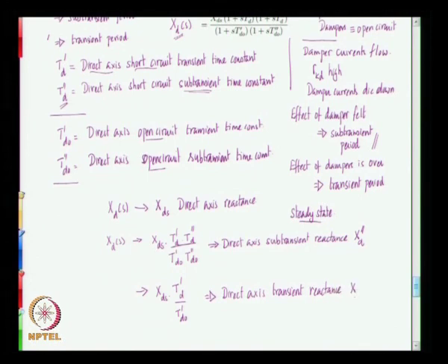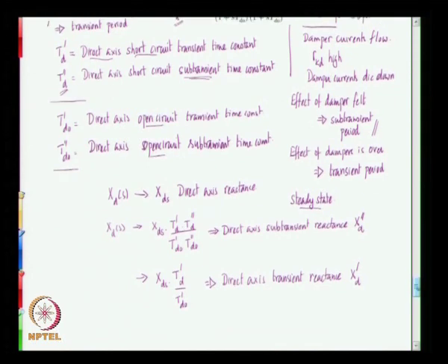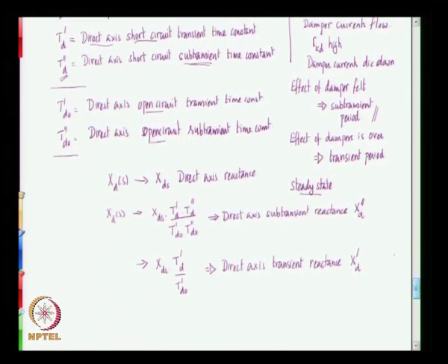This is given the symbol x dash d. Now these are representative, or these give an indicative idea of how fast or of the magnitude of disturbances that may be there in a fast varying system in case of this alternator.